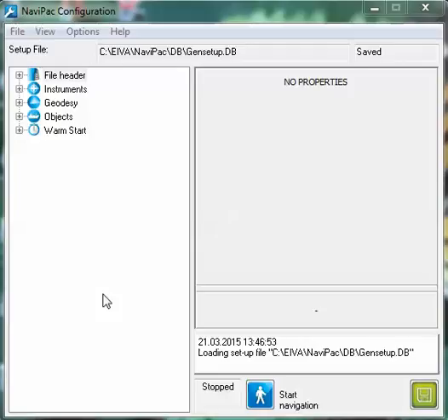We start this EVA training by opening NaviPark configuration first, as seen. Now, one of the things we're going to be doing is to add instruments, and in EVA NaviPark configuration, at least 2 instruments must be added, which are surface navigation instruments, talking about DGPS, differential global positioning system equipment or instrument, and a gyro. You can use meridian surveyor or azimuth flush gate or whatever other kind of gyro that is available at your use.